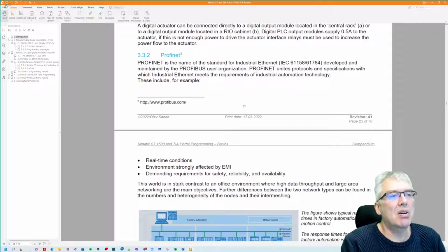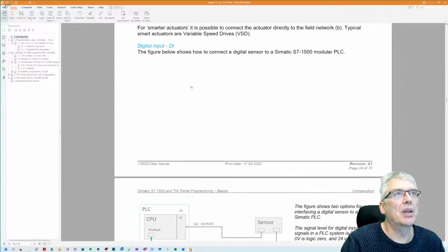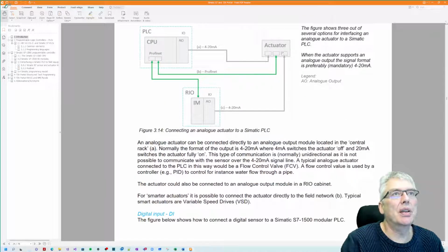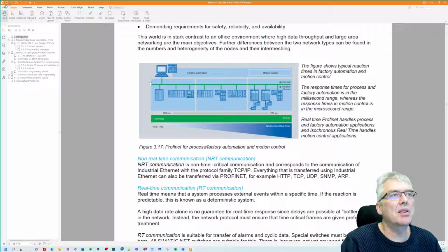Down here in the last is Profinet, which is, see if we go back up here, this one, the Profinet, the serial communication. You can just look at the figure, you can read this, but Profinet is a network which connects a lot of devices. Here's a PLC. This could be, for instance, an HMI panel. This is probably a CNC controller, another PLC. Here is the remote I/O we talked about. Also remote I/O. Here we can have drives, a frequency converter, controlling motors, and so on. And then we have motion control.